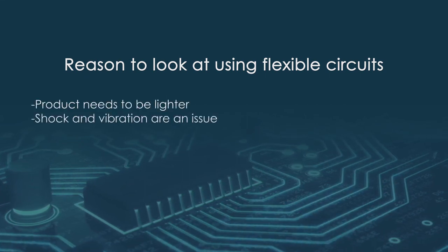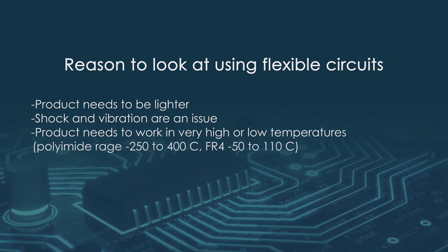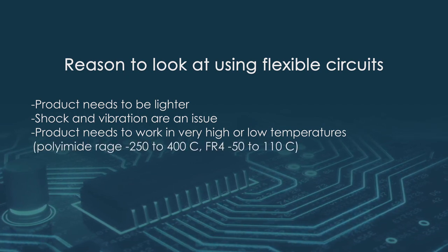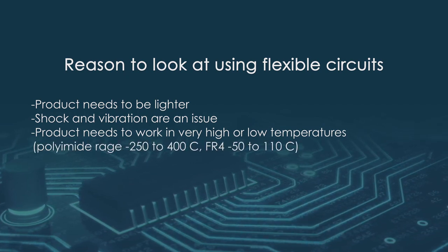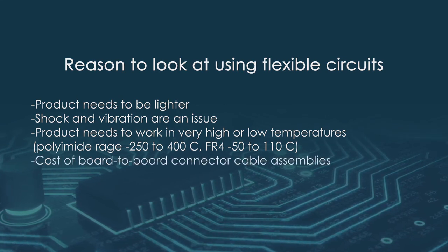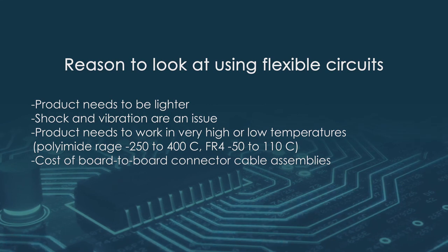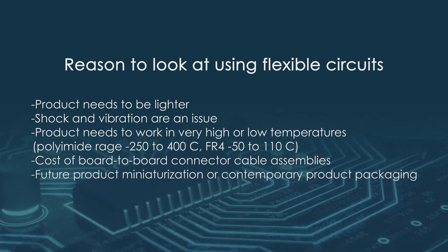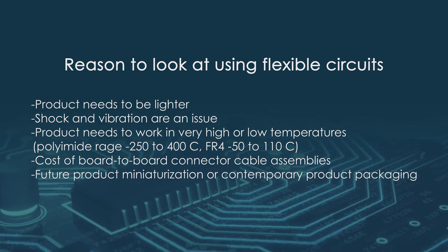Shock and vibration are an issue. Product needs to work in very high or low temperatures. Polyimide temperature range is -250 to 400 C, where FR4 is -50 to 110. Cost of board-to-board connector cable assemblies is an issue. Future product miniaturization and contemporary product packaging.